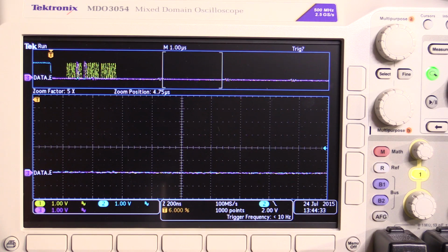And it's not even the loop. If I actually take out the call to the SPI, it can run this entire loop with 65,000 odd iterations in about 30 milliseconds, which means that you should be able to get several kilohertz of sine wave out or more from the Raspberry Pi if the SPI bus was working more efficiently, but currently it's not. Now, that's not a showstopper, of course. You know, you can use a microcontroller as your physical interface if you wanted to.